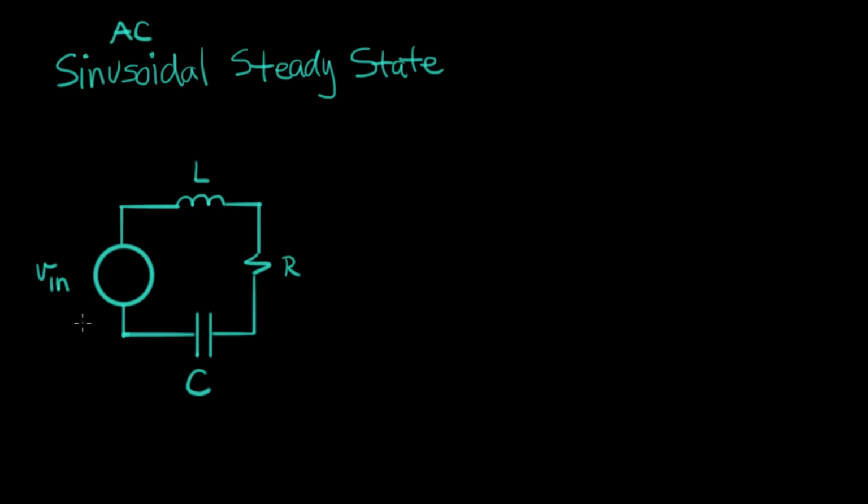So let's first take a look at this circuit here. This is now a driven RLC circuit. So here's the drive function. It's a voltage, some waveform, driving a sequence of an inductor, a resistor, and a capacitor. Now, in an earlier video, we derived the natural response of this circuit. To do that, we removed the source and shorted it out, added a little bit of energy to this circuit, and saw what it did on its own, what its natural response was. And now we've upgraded this. We've added a source, and now we have to solve this again, including the source.